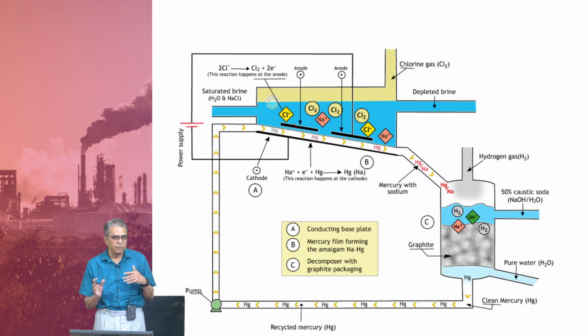After a lot of trial and error, people first started with carbon, because the easiest thing is, carbon conducts, everybody knows. So, graphite electrodes were made, then the graphite has to be made into a plate. So, you have to have a binder. Over a period of time, this chlorine ate up all the binders and this collapsed. So, one after the other, finally people went into titanium based electrodes. So, that is how this was.